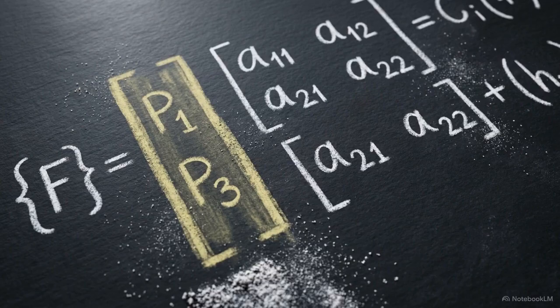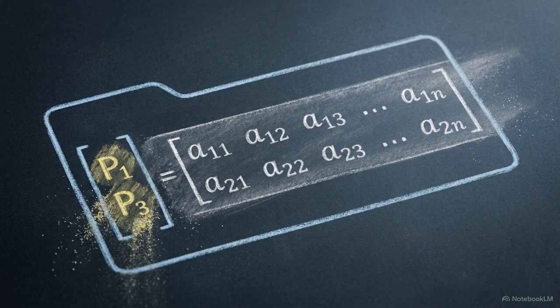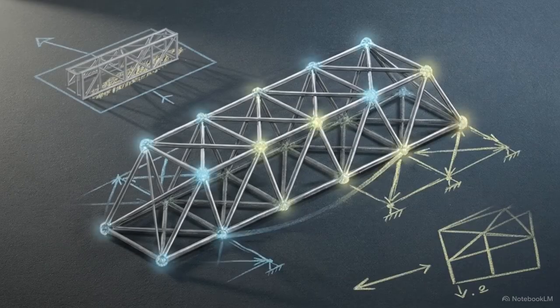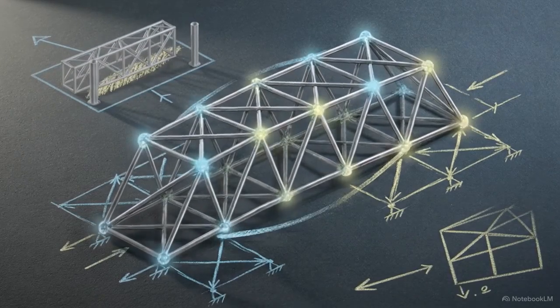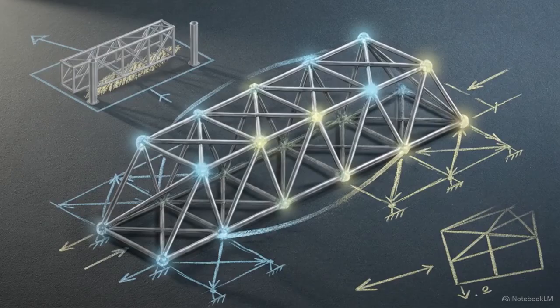The 2 rows we pulled out, rows 1 and 5, contain the unknown vertical reaction forces at the 2 supports. We define these extracted rows as the secondary or auxiliary set of equations. The physical topology of the supports directly dictates the geometric shape of the solvable algebraic core within any finite element model.